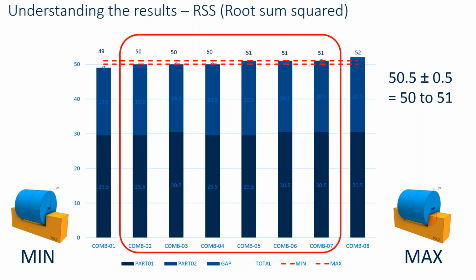As you see, most of the combinations will fall within the tolerance zone. It is more likely that our manufactured part would fall within the accumulated tolerance than not. And of course, instead of dealing with the worst case scenario, where possible combination of tolerances, a statistics approach allows us to deal with the most likely combinations of the tolerances that we're working with.